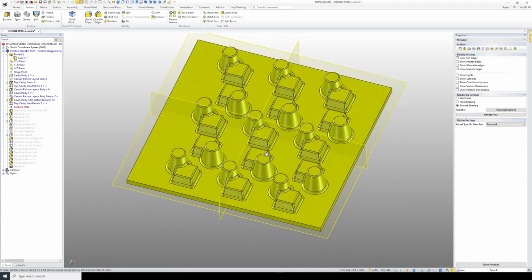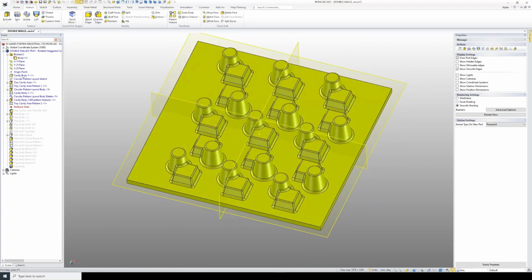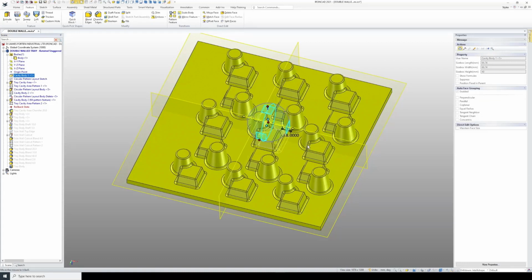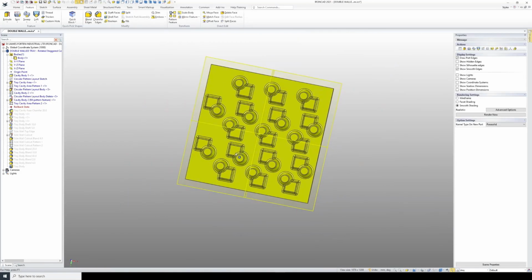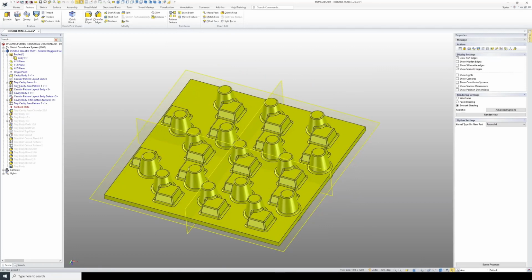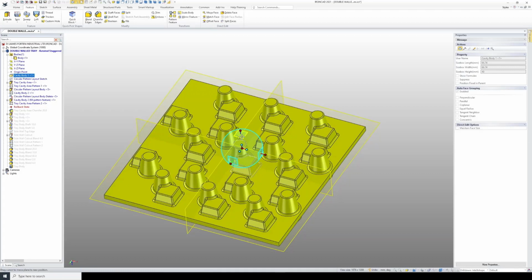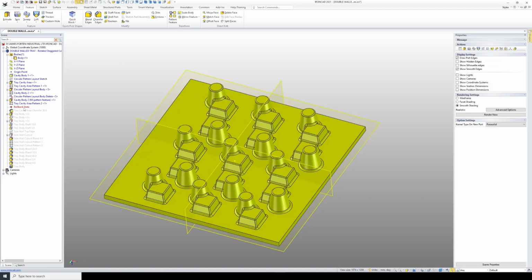I'll recalculate, and again if I move it 18 millimeters this way, it should regenerate over here and give us a better fill as well. Good. So that's all behaving as it should. So I'll move that body back to originally where it was, lock that top face, and I want that at 0, 0. And all going well, I should be able to roll back to the end.